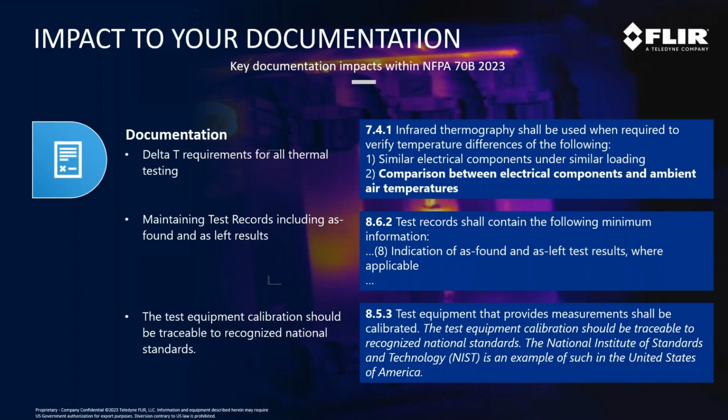And what that means is as repairs are done, documenting that the repair was completed, and here's the new thermal image maintained, new thermal analysis done to show that the repair was done. So it's important that those test records contain that information. That is line number 8 of, I believe, 10 or 12 in section 8.6.2. There's a variety of other things that test records need to contain, but I wanted to call this one out specifically as it pertains to thermal.